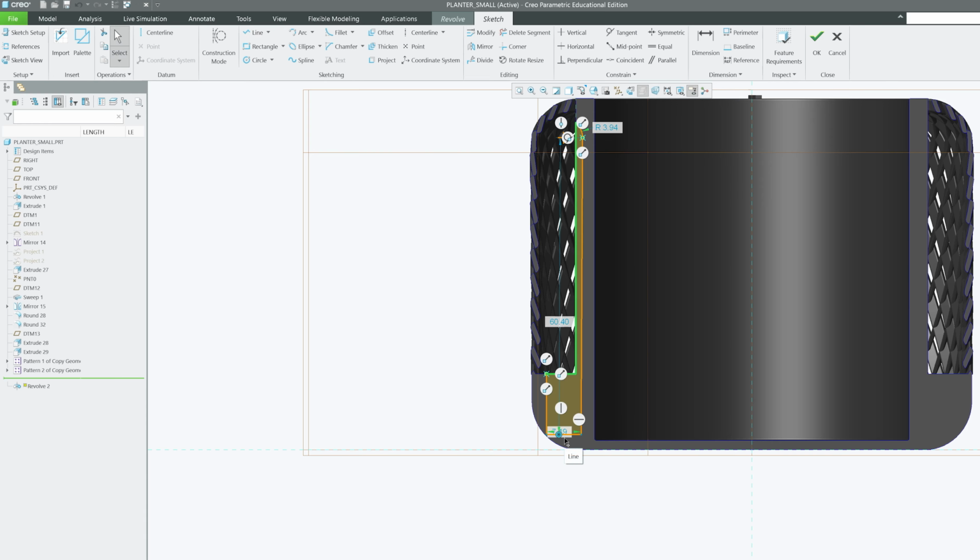All these parametric modeling software, be it Creo, CATIA, SolidWorks, you name it, use CPU compute for any kind of calculation. And when we talk about CPU compute, they do not offer parallel processing. So let's say you have a 64 core CPU, it simply doesn't add any value. These 3D modeling software will only use a single core, and the thing that matters is single core performance.